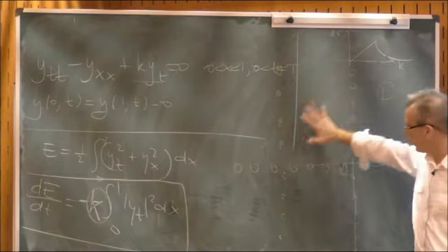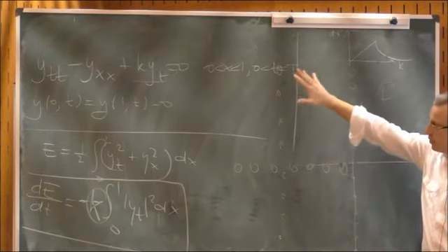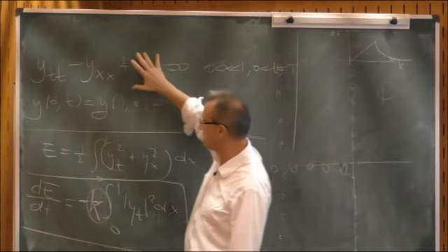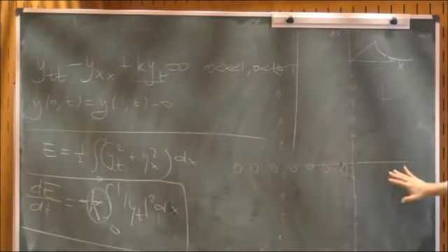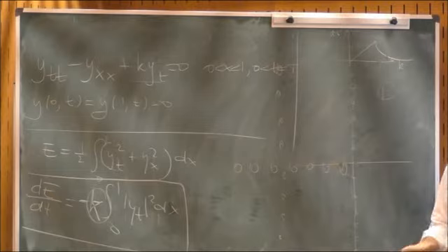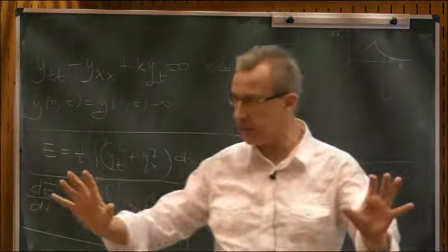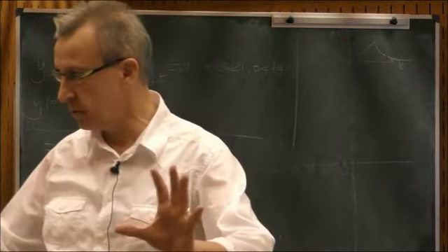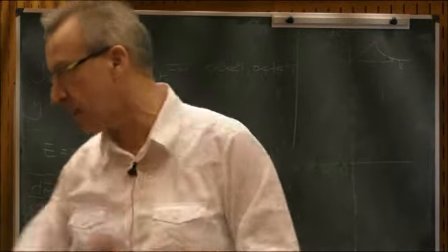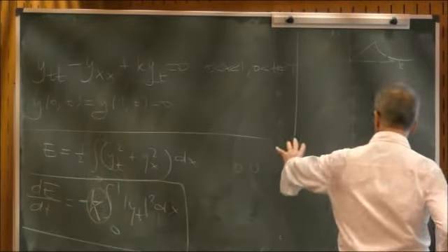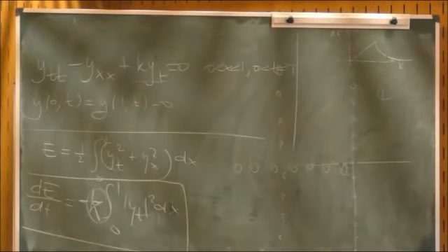So this is the fact that these are non-self-adjoint operators, because this is a damping on a conservative system. So these spectra are not self-adjoint, so they are on the complex plane. And there is no way of pushing a complex spectrum in a uniform manner. You push here and then the others are moving in the opposite direction. So you have to be very careful. So the design of dampers is delicate.